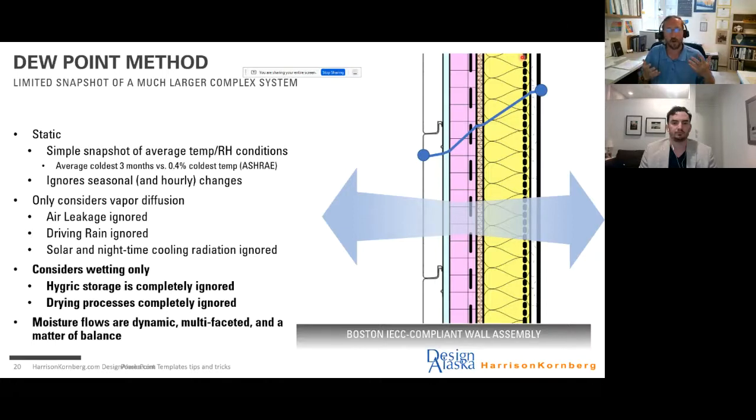We know, like Charles said, water wins. Water's going to get in from the outside through flashing failures, through time, through damage, through little holes that mice chew into things. And then moisture is going to get in from the inside, especially in cold climates, through little holes in the air barrier, and having that humid air flow through our wall assemblies and find a condensing surface.